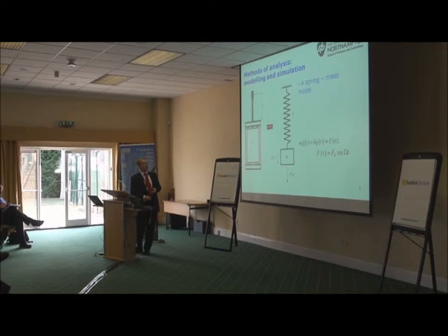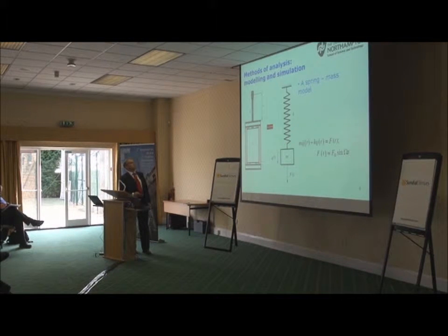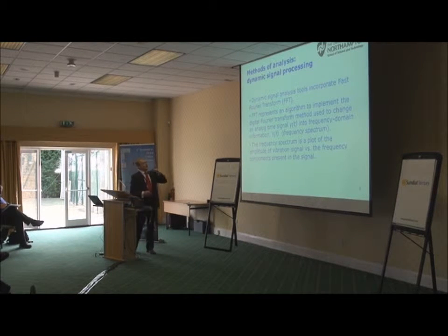We can solve this equation for the unknown quantity Q, which is the response, if we know this force. Typically if this force is harmonic, it will have two components: the frequency omega and the magnitude. We can also calculate the natural frequency. And when the frequency calculated from this equation, from the left-hand side, equals omega, we have resonance. I will talk about this phenomenon very briefly a bit later.